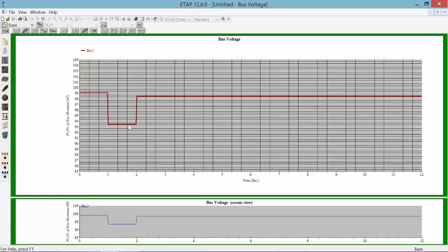For about a second we had this motor accelerating up until the second, which is running at its full load, and the voltage level now is around 98.5. It's because motor 1 is in line because of event 1. And as you can see again, the reason why you're seeing a flat line during the acceleration is because we're running the static analysis.